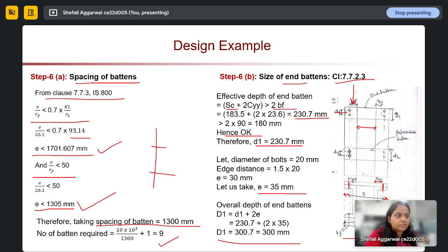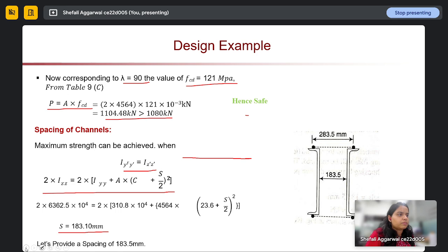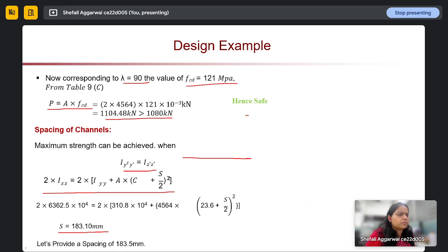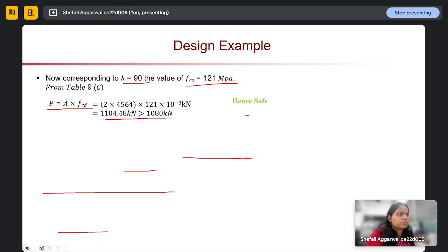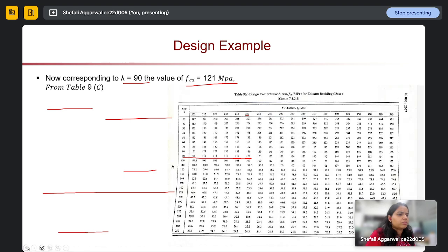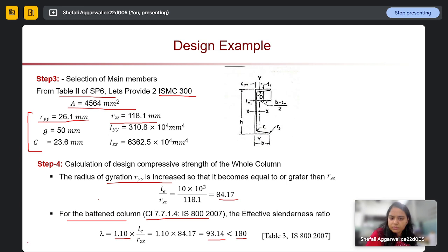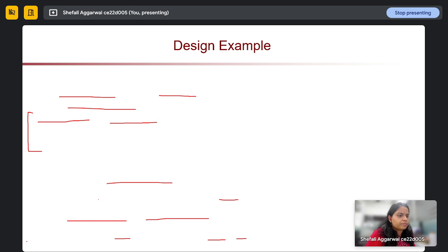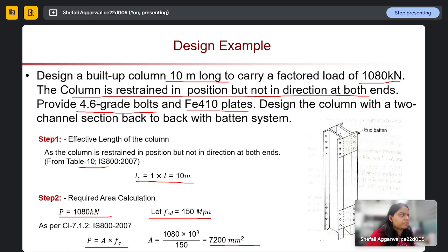I mean, we didn't see this kind of longitudinal stress in the previous lacing system. In a lacing system, you don't get this kind of longitudinal one. Lacing is placed diagonally, and along that we are getting axial force. I felt this is like a second, other kind of load. Why is this kind of load not seen in the lacing system?